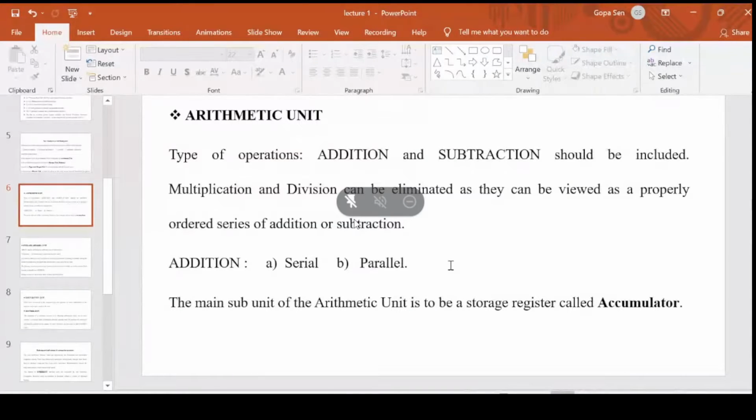Now here I stop and ask you, you have already learned full adders and half adders in your previous classes, yes? Yes, ma'am. So what does a half adder do? A half adder adds two binary bits only. Whereas what is the purpose of using a full adder? A full adder can add two bits as well as the carry from the previous stage. And the output of the full adder circuit is a sum output and a carry to the next stage.